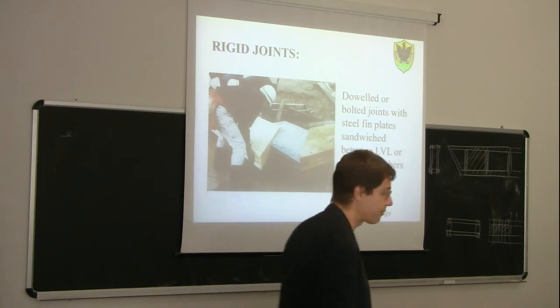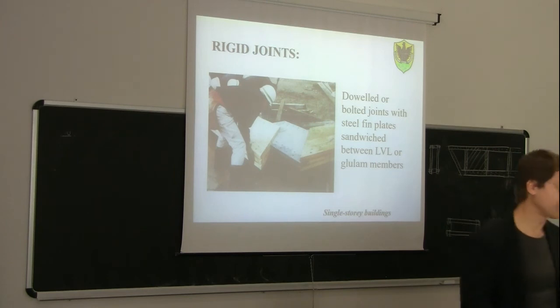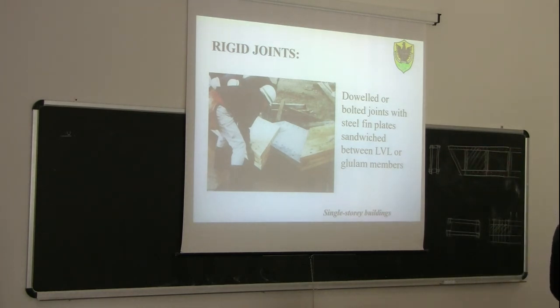When we are talking about fire resistance, you will see that contrary to what one may think, it's better to have wood outside rather than steel. Wood is combustible, steel is not, but wood is also a good insulator, while steel is a good conductor. So if you expose a steel plate outside a timber structure, in the case of fire, the steel won't burn, but it will conduct the heat very quickly inside the wood. And then you will have lots of problems inside. But if the steel is inside the wood, in some way the steel is protected by the wood. So the wood will burn outside, but since it's a good insulator, the steel will still be at a lower temperature because the wood is going to insulate the steel itself.